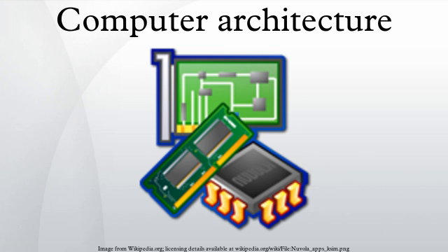Power consumption. Power consumption is another measurement that is important in modern computers. Power efficiency can often be traded for speed or lower cost. The typical measurement in this case is MIPS per watt. Modern circuits have less power per transistor as the number of transistors per chip grows. Therefore, power efficiency has increased in importance. Recent processor designs such as the Intel Core 2 put more emphasis on increasing power efficiency. Also, in the world of embedded computing, power efficiency has long been and remains an important goal next to throughput and latency.